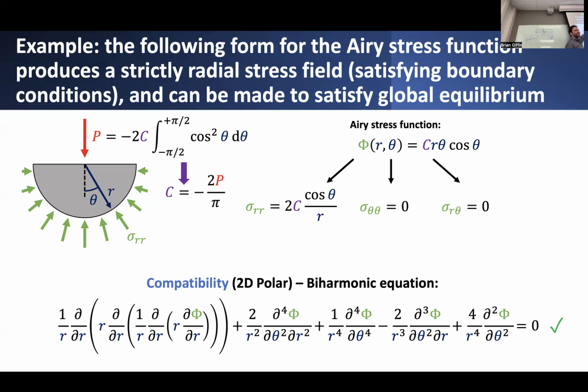and we just defined some boundary conditions that we know at least satisfied this kind of equilibrium condition in a global sense, then we could just pick any darn distribution of stress on this boundary that we wanted. And interior to this domain, solutions will look the same far enough away from the boundary, according to Saint Venant. So we can proceed along those lines and just say, well, it's a solution to some problem. And if we take the plate to be large enough, then it's a solution to any problem, assuming that we're far enough away from these boundaries. So in some ways, you can fudge your representation of these problems and still use rather general approaches that kind of employ these tricks, if you will.